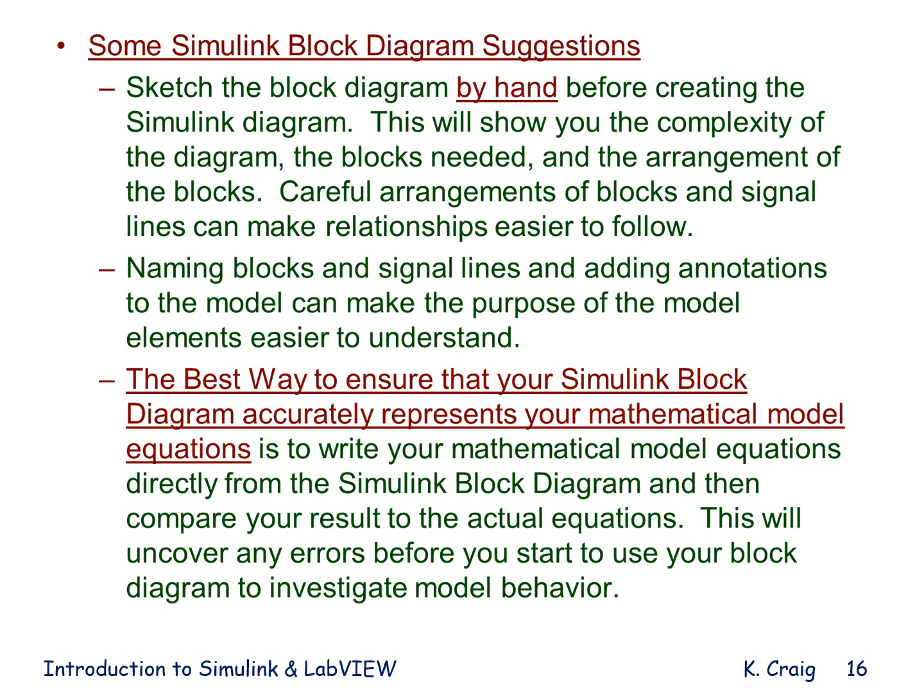Secondly, naming blocks and signal lines and adding annotations to the model can make the purpose of the model elements easier to understand. Your Simulink diagram must be understandable without you being there to explain it. This has to be usable by other engineers without you being there. So it has to stand alone by itself. You need to annotate your diagram and have it be complete, thorough, and self-explanatory.